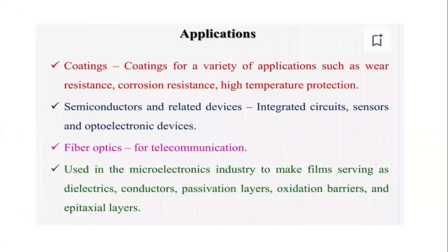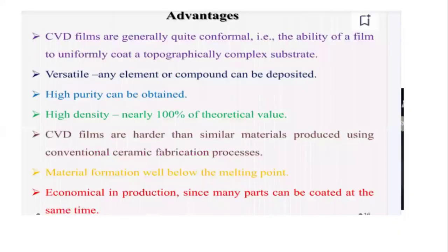Applications: coatings for a variety of applications such as wear resistance, corrosion resistance, high temperature protection, semiconductors and related devices, integrated circuits, sensors, and optoelectronic devices, fiber optics for telecommunication. Used in the microelectronics industry to make films serving as dielectrics, conductors, passivation layers, oxidation barriers, and epitaxial layers.